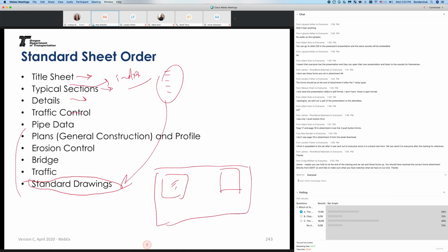You will find a table here which shows ramps, elevation, slopes, ramp number, the LRM number, the corner number, and design exception, and so forth. So the detail sheet, once you open it, has all the ADA information needed to put in the inspection form. This information inserted in the plan sheets is crucial for the inspector, the designer and the contractor to follow when they fill out the inspection form, because it's all built on this.